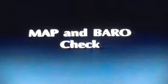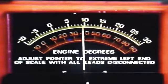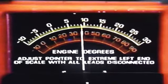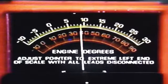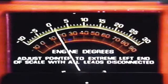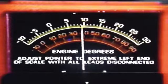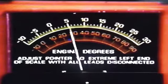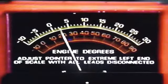The next thing we want to do is make a final MAP and baro check. To do this, we start the engine and run it until the timing is stabilized. We then unhook the vacuum hose from the MAP sensor and should see the timing retard. When we reconnect it, we should see the timing change back. Next, we add vacuum to the baro sensor, and the timing should also retard. If this happens, we know we have proper function in these sensors.